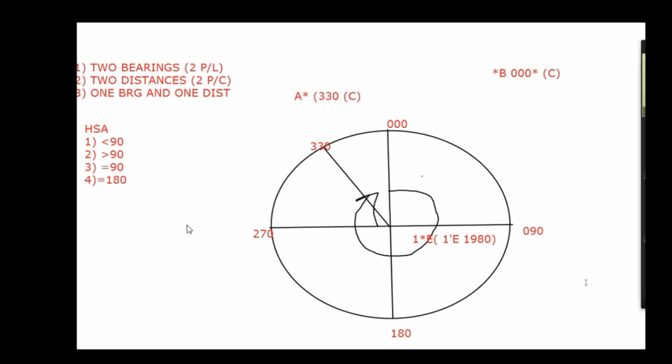The moment you change the course, your compass error changes. Why does the compass error change? Variation remains the same because it is the same place, but the deviation changes. So compass error depends on two factors, variation and deviation, and deviation depends on the course. And the deviation card, if you have seen on a ship, gives the deviation for every 10 degrees of compass heading or compass course, in the compass card on board. Every ship should have a compass card.